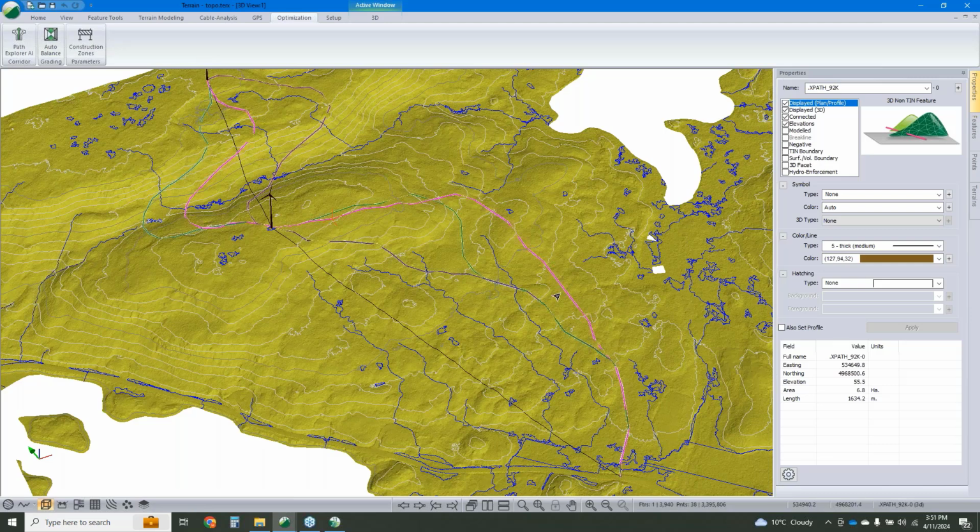In actuality, if you were laying that out, you're probably taking into account a lot more nuances. Plowing through that little hummock there results in moving more dirt. So if you were laying this out by hand, you'd probably avoid going through that hummock. But if you're costing it in terms of dollars per linear meter, you might not capture that difference. So we do need to consider it in terms of dollars per cubic meter to get a reasonable solution.